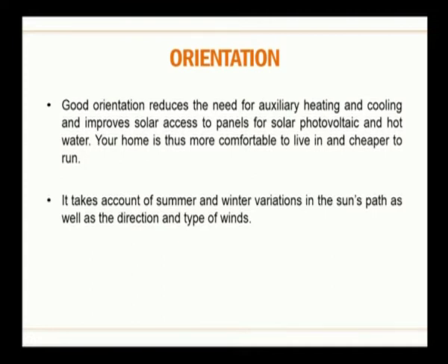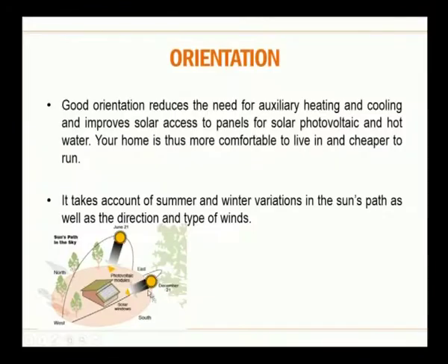So, when you are making design decisions, you also should refer to wind rose patterns, which inform you of the prevailing wind directions and towards which you should or should not orient your building. If you are in a colder region, you would not appreciate a cold gush of wind coming to you, but when you are in a tropical region, a wind breeze is much appreciated or much expected. So, you have to orient according to the prevailing wind direction, which you can learn from the wind rose pattern of your location.